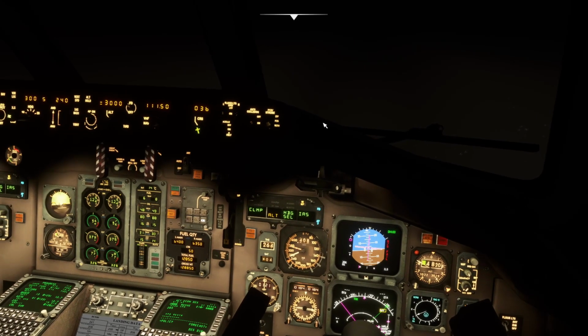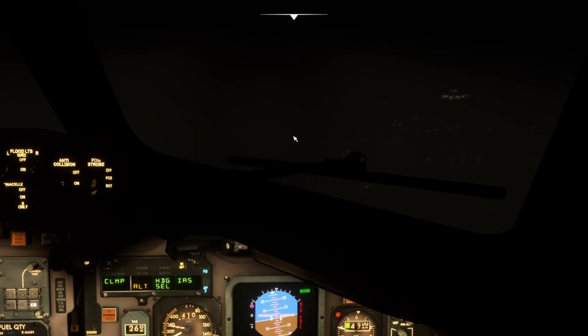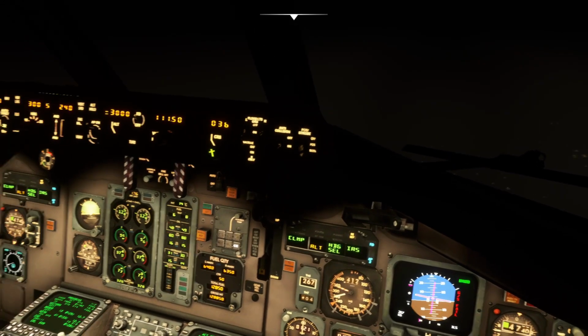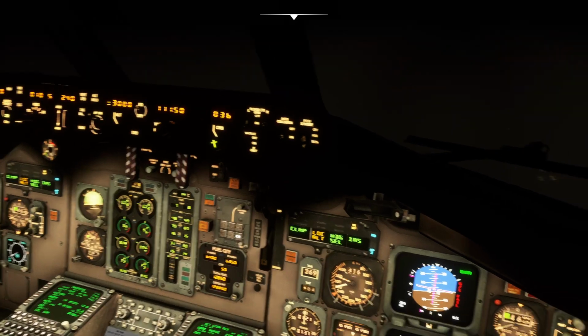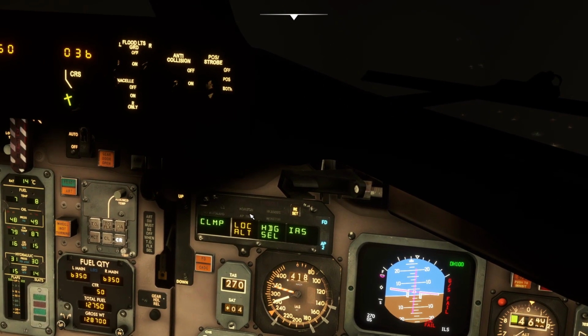So down we go. And I guess we're out of range at this point for it to be glide slope fail. Delta 1623, turn right heading 010, intercept the localizer. Heading 010 for the localizer, Delta 1623. So 010 is bugged, and we'll click VOR loc to arm the localizer capture. And now you can see we have two parameters armed, altitude and localizer.